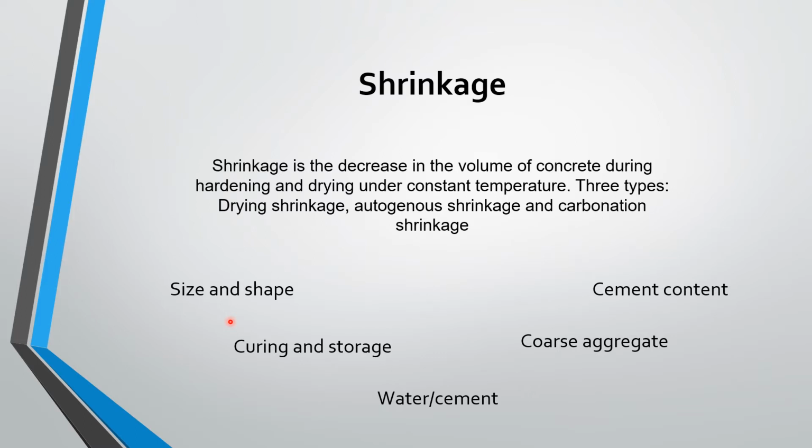The last one is carbonation shrinkage, which is basically the shrinkage caused by carbon dioxide rich atmospheres. The causes of the shrinkage are cement content, curing and storage, water cement percentage, coarse aggregate, and cement content and type.